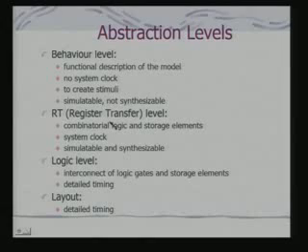Next, from the behavior level we come to what is called the register transfer level. At the register transfer level we specify the activity in terms of combinational logic and storage elements. We specify the system clock, because the storage elements would actually be flip-flops. So why is it register transfer? Because I can specify the behavior of the circuit in terms of data transfer between different registers, and while the data transfer takes place the data gets modified or transformed using your combinational circuit. That is exactly how you have designed your digital circuits.